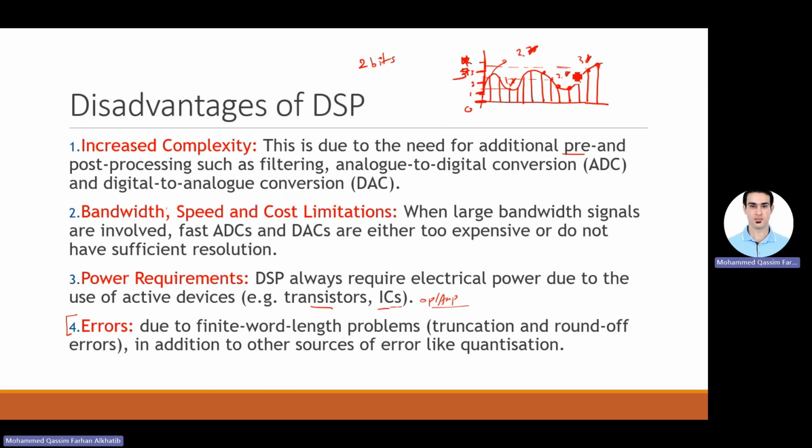So that's what we call quantization. I'm giving these samples a quantity. Now, because of this, I'm getting an error. How to reduce the error? Increase the levels. So I have now 3 bits, for example. And with 3 bits, how many values can I get? 8, from 0 to 7. So analog values are the same, but I have 7 levels: 0, 0.5, 1, 1.5, 2, 2.5, 3, and that's it. Now I can approximate: the first level is 0, 0, 0. Second level, 0, 0, 1.